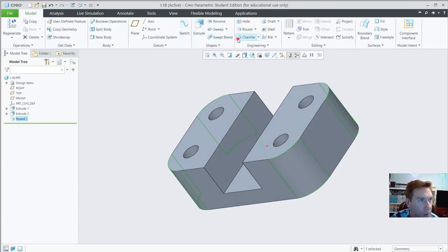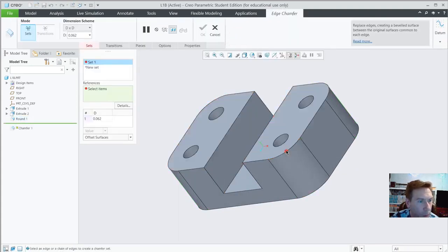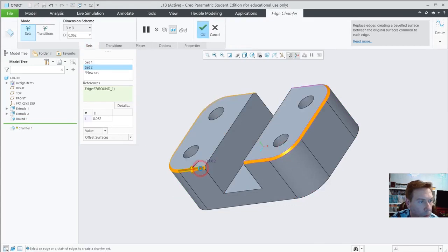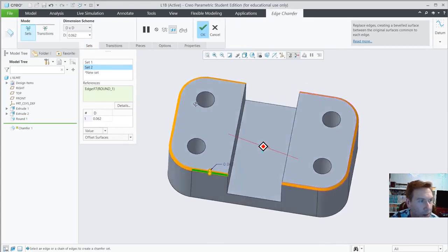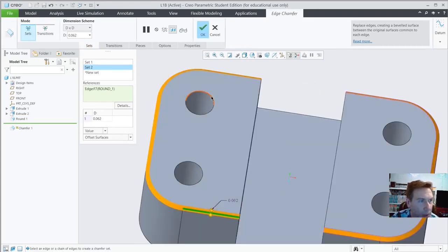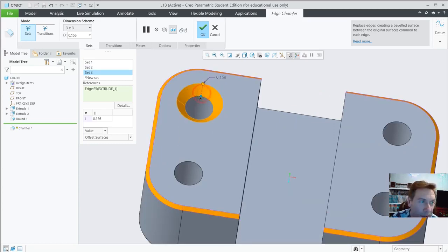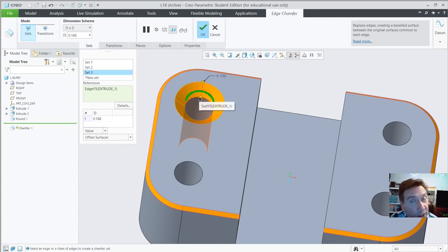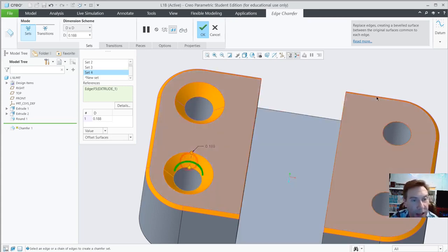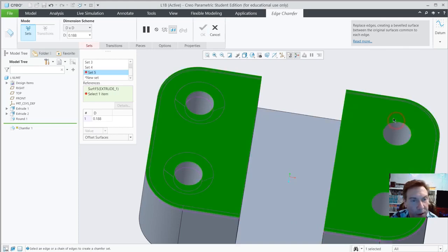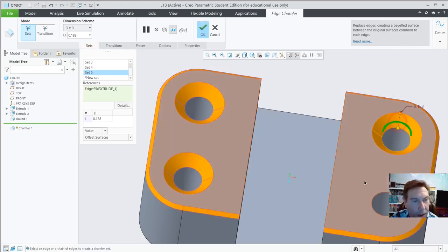Let's go to the chamfer tool. Now, if you add a chamfer to an edge of a hole, you've got a countersink. So you could actually use this for countersink. But the hole tool, which we're going to learn in exercise 4, has a countersink built in automatically. It's really pretty nice how it works. So you can do it this way or, oops, however way you want. I'll just add those.